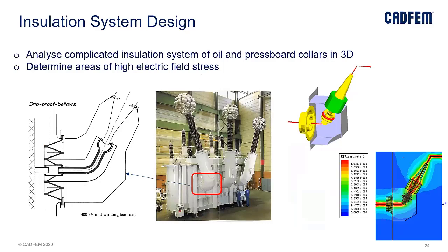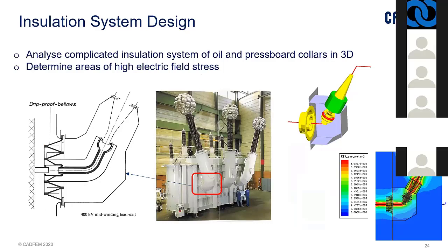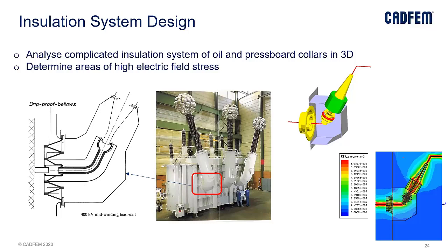Apart from that, here we are addressing a few more complex insulation system designs, like pressboard collars or the oil-based pressboard collars. We are able to address this. The reason why we are mentioning this is that once you understand the electric stress behavior on these particular insulating materials, it will give us an idea of the stress accumulated on these insulators.